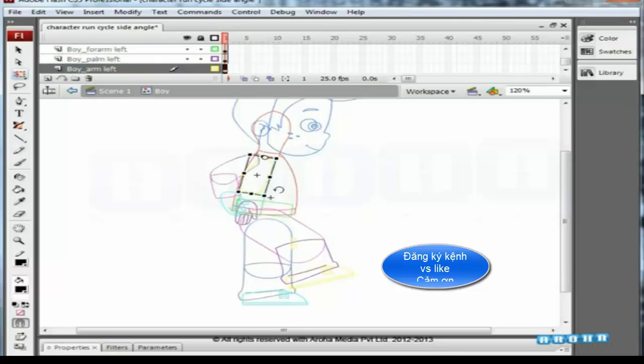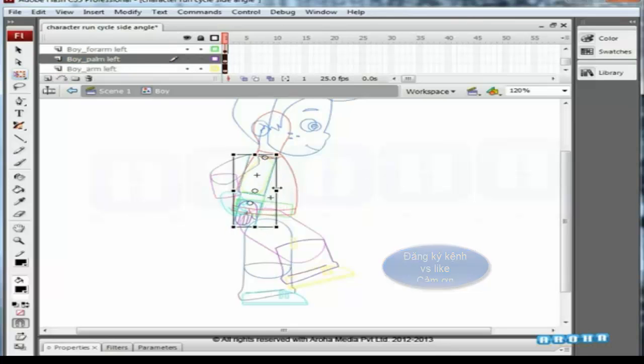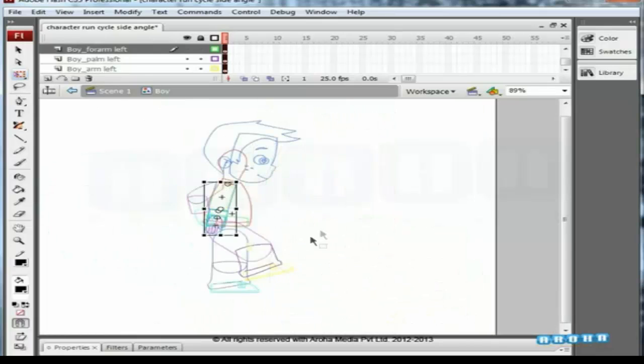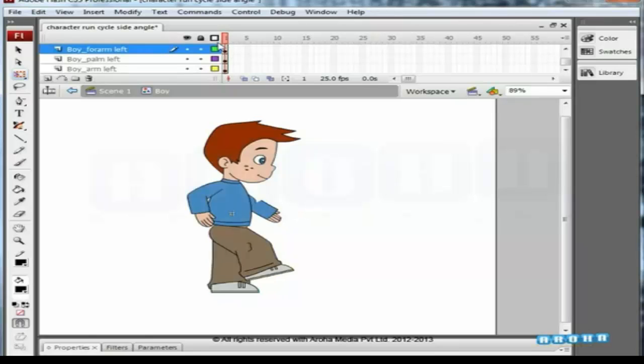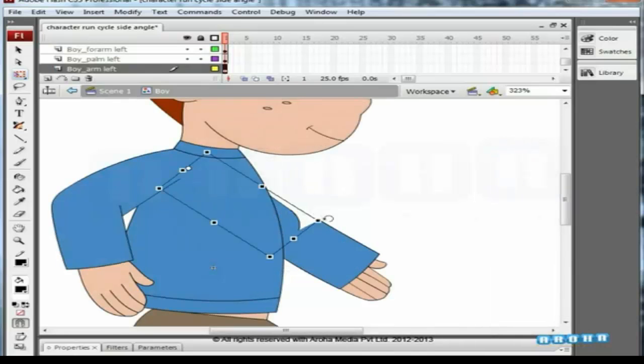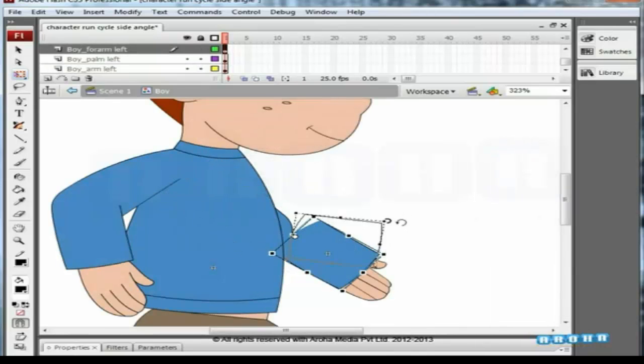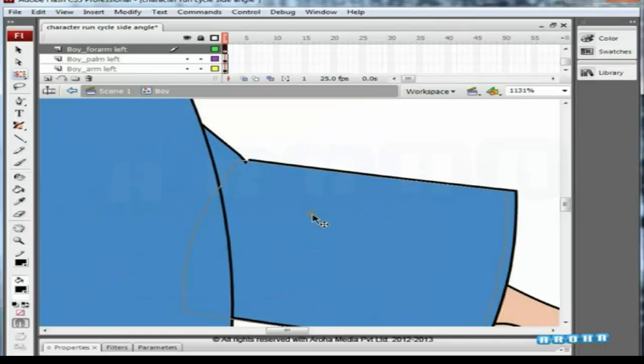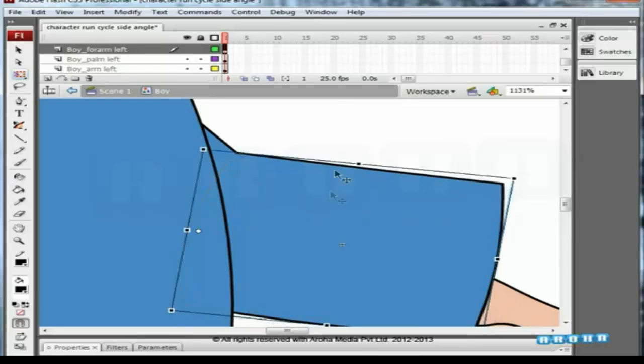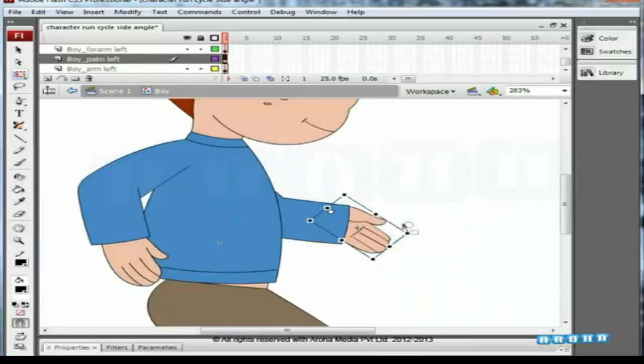Switch on the outline mode to pick the hidden left hand behind the body. Notice that every time before moving any multiple parts together, we are adjusting the pivot points as per the direction they are going to be rotated in. The hand placements are done.